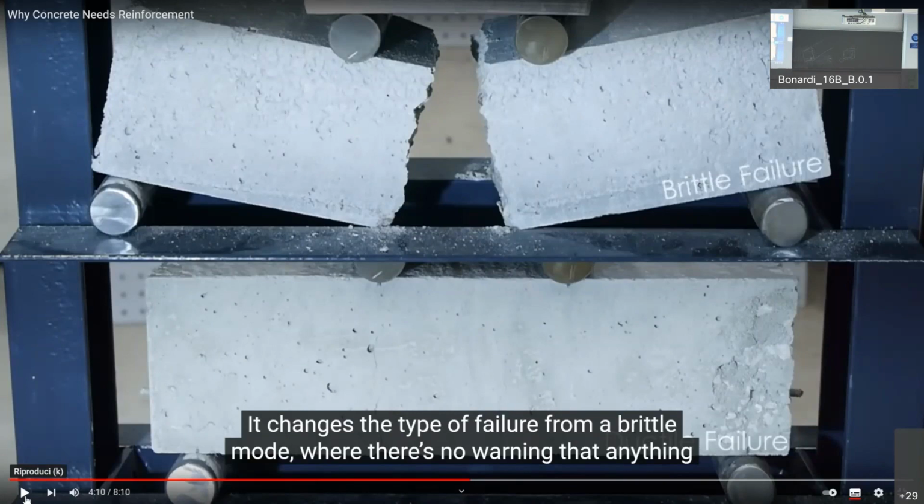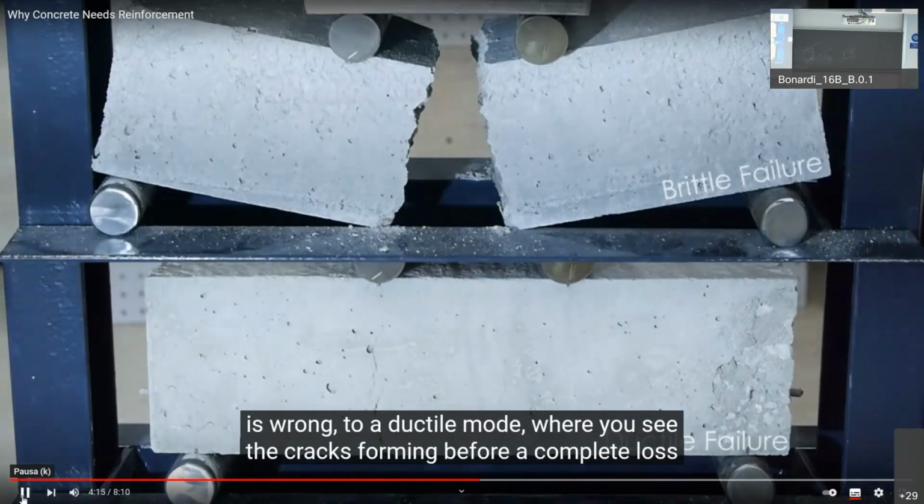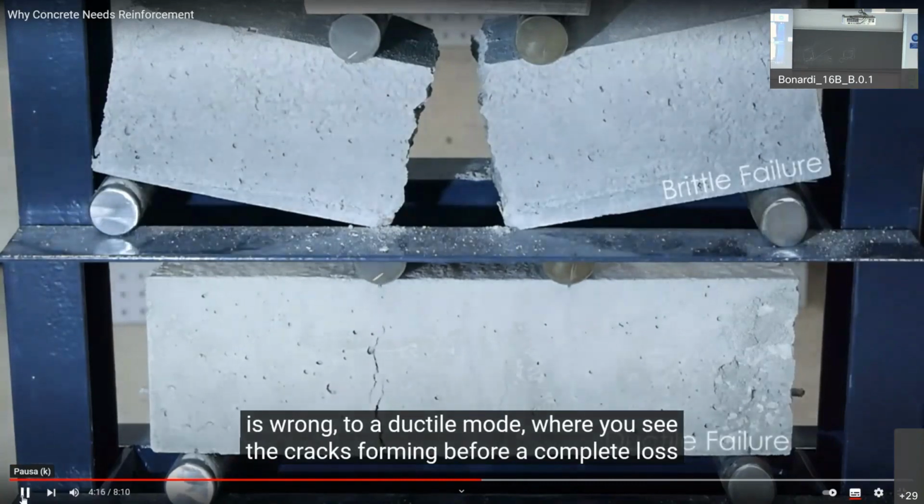The opposite behavior is the ductile behavior, duttile in Italian. That means that the structure, before failing, undergoes greater and greater displacement. And that's important because it allows us to understand that something is going wrong and that we can just walk outside the building before the failure.